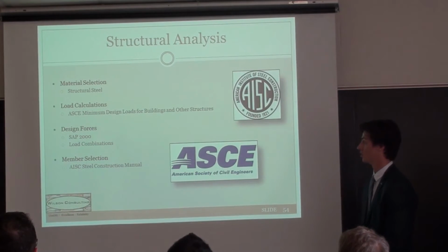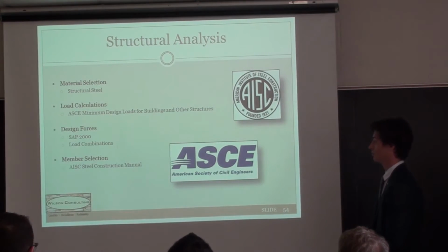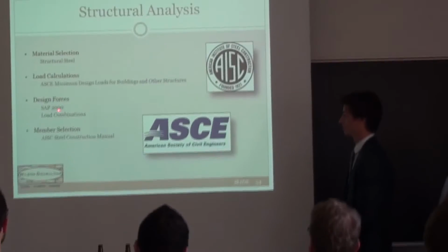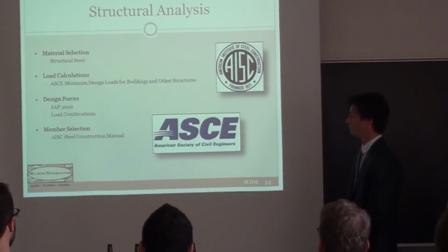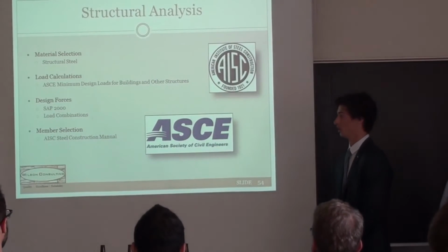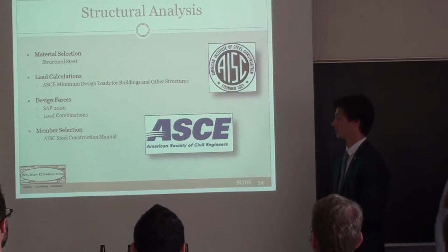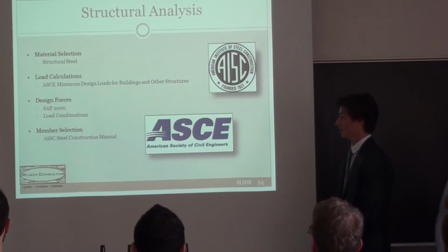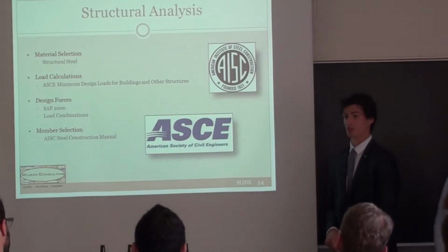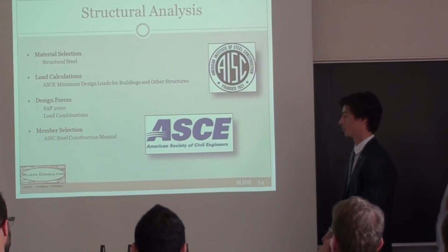Once I calculated the loads, I built a model on SAP 2000 computer software. This allowed me to run my load calculations onto the model, and it spit out a number of design forces in different combinations. The load combinations that governed for this design were load combinations 2 and 3.